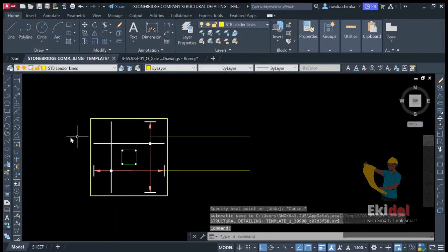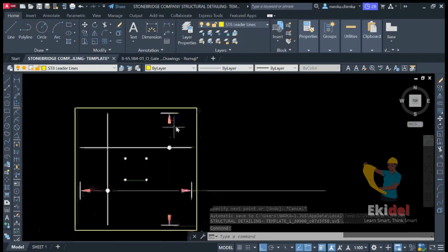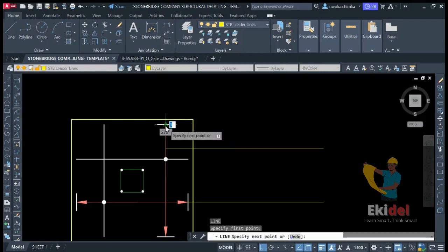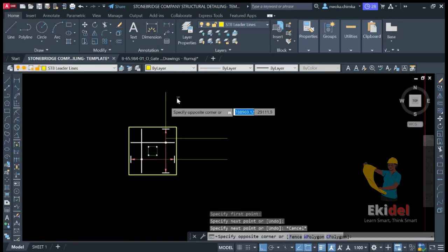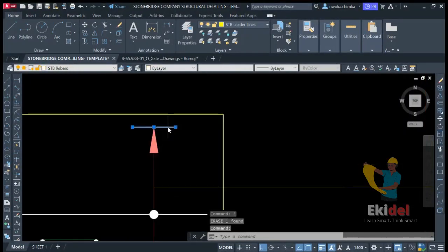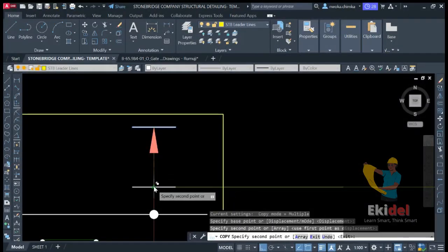Now, because we have done this, since we didn't take this point from this arrow here, we want to number all our reinforcement from this direction and not show it this way. Although most people can show it this way if you want, but just to make sure everything is well aligned, I'm using one side direction to number my callouts. So I'll just copy this, copy CP, and then copy it to this point to show that I'm pointing this.